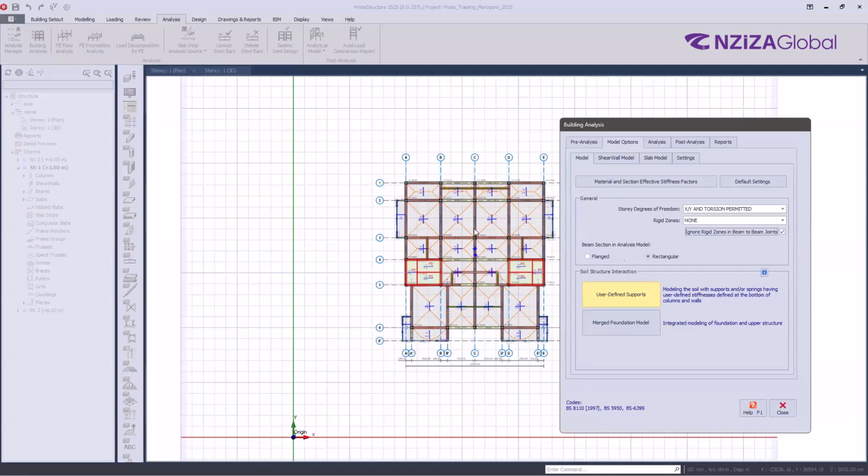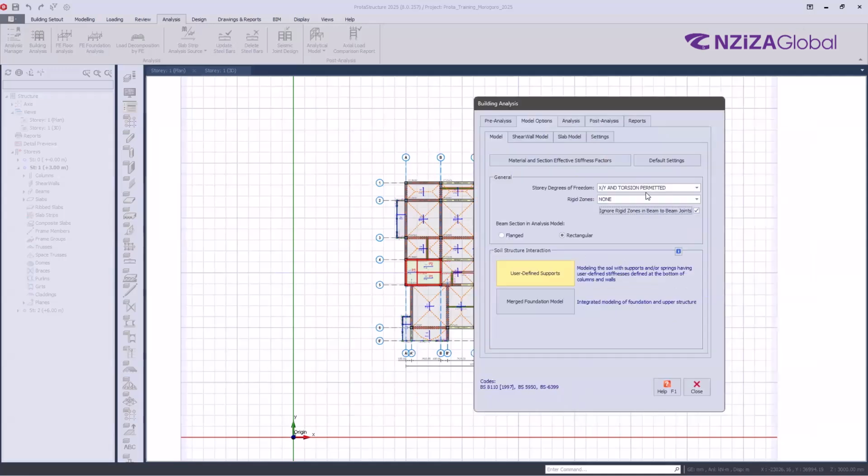So it means we don't have to use none. If you use none, it means you are saying that there is no rigidity, which is wrong. So for our case, the none option is not permitted, if I can say, because we are dealing with reinforced concrete members. The column and the beams are cast monolithically, so we have a rigid zone, so we must consider the rigidity. So we remain with the 3 options.